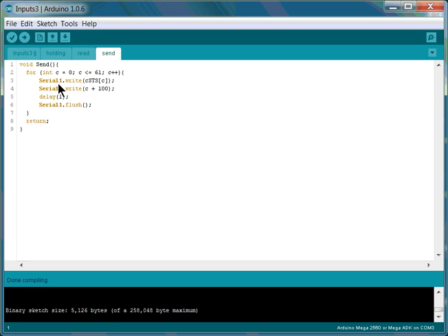Then I take and I send over within the loop Serial1 write, current status C0, send that over, whatever that is. It could be 1 or 0, I don't know, but I send it over to the output Mega. Then I Serial1 write out to the output Mega, C, in this case 0, plus 100. So it's sending over 100.